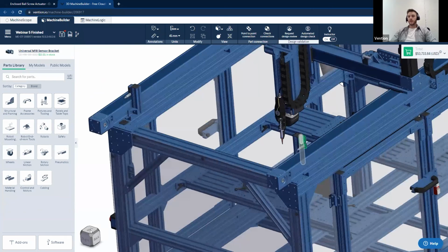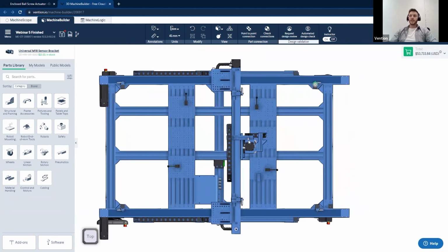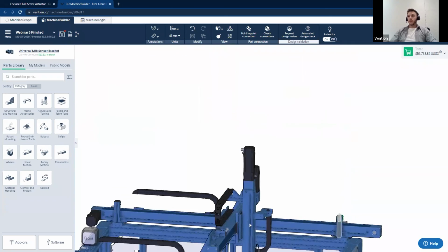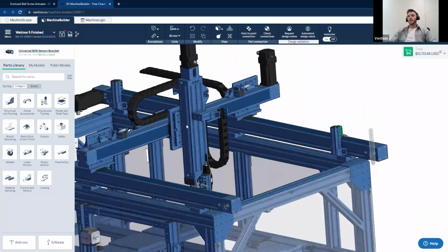The reason being, if I do a top view, if the actuator travels all the way to the far right side, the Z-axis will impact the edge. With this, it prevents the impact from happening. And we have replicated this on the X-axis as well. For the Z-axis sensor, there is nothing hindering its motion, so for those you can use the standard sensor ports.